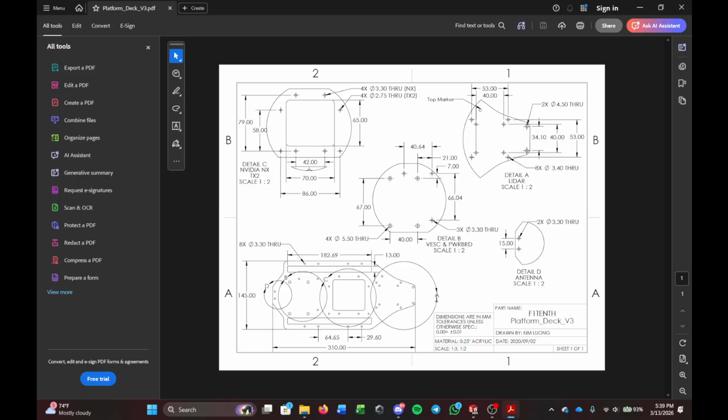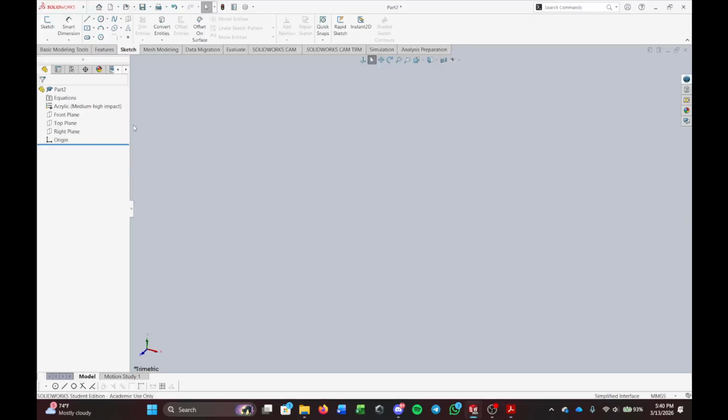So quickly now, I'm gonna look at the drawing document again and get an idea of where I want to start. I'm basically just making a plate, like a platform. If we think about that, that's not too complex. So jumping back into SolidWorks now, we have features, sketch tab, and whatnot. We're gonna be working in the sketch tab because you want to sketch your 2D surface, or quote unquote object, and then extrude that into a 3D object.